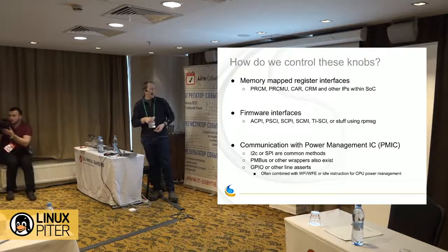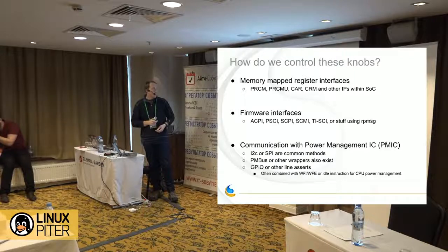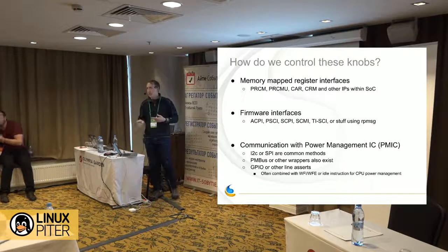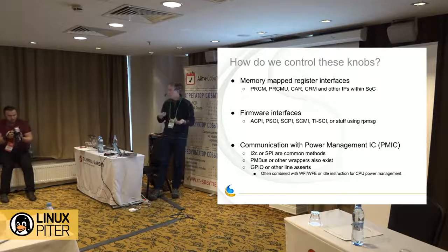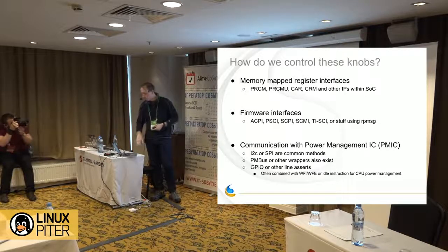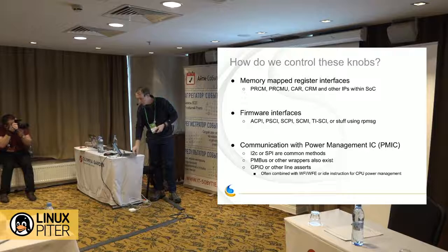There's also bespoke communication with power management ICs. A lot of times they're wired up to an application processor over I2C, and there's some message passing back and forth to control the power state of the chip.